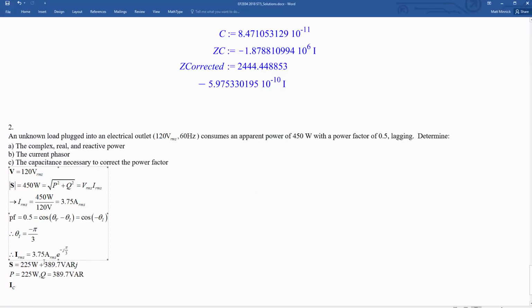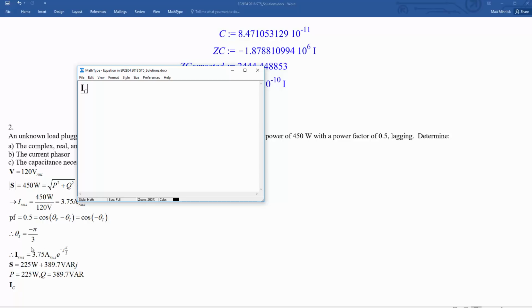And it is going to be canceling out this part. So what we want is that the current that we're adding is going to be completely imaginary and cancel out the imaginary part of this. So what we need is that this thing is equal to J times, well, let's say it's equal to negative the imaginary part of the RMS current that we've got already.